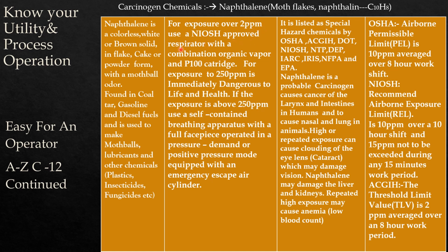Use a full facepiece respirator with a combination organic vapor and 100 cartridge. Exposure of 250 ppm is immediately dangerous to life and health, IDLH value. If the exposure is above 250 ppm, use a self-contained breathing apparatus with a full facepiece operated in a pressure demand or positive pressure mode, equipped with an emergency escape cylinder.